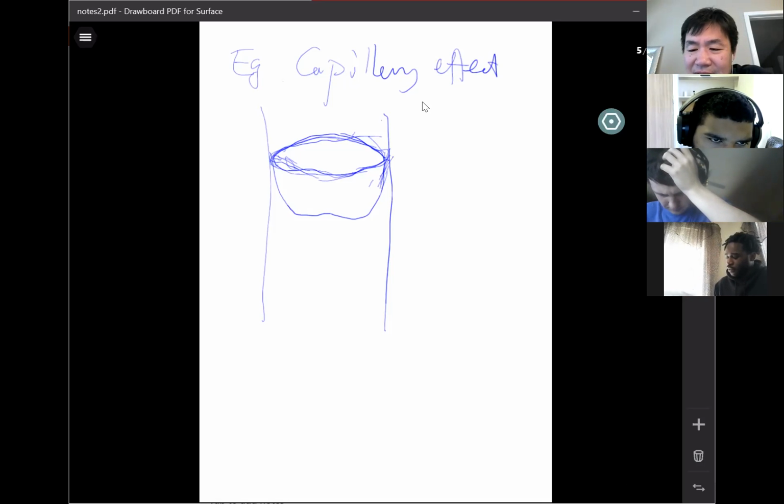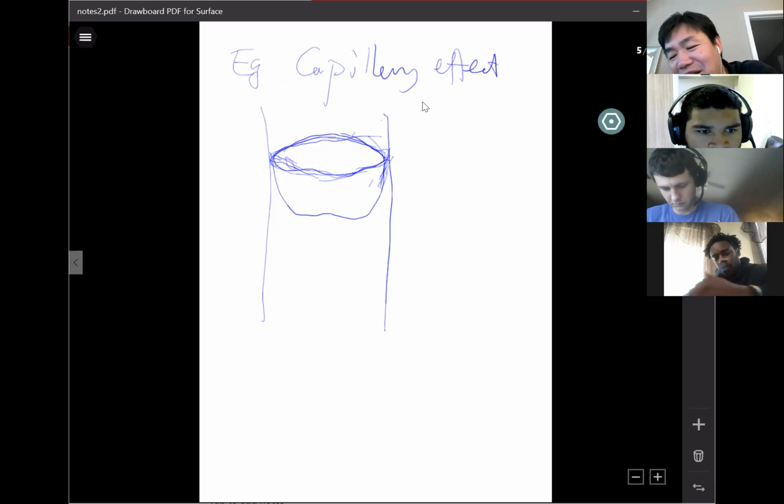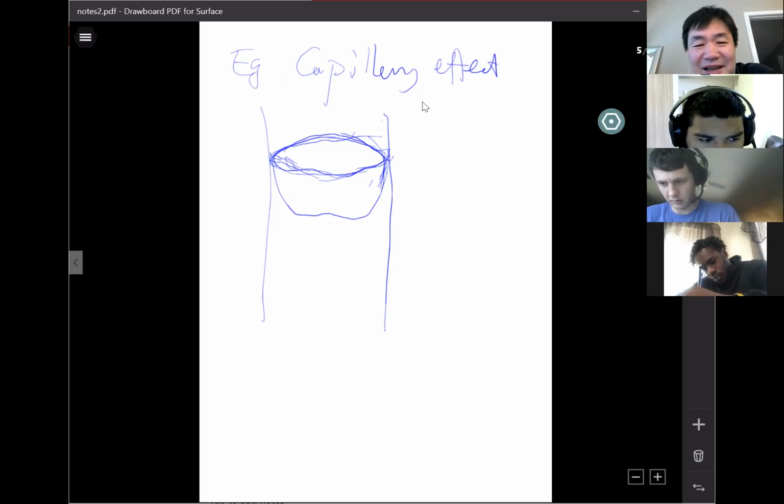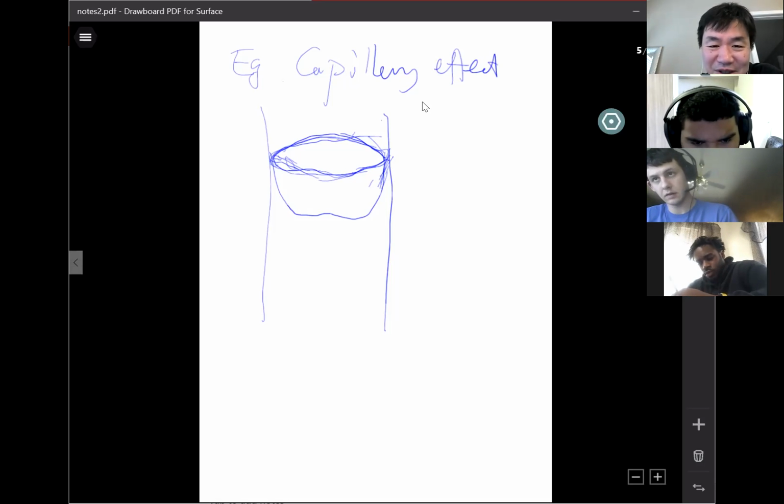Surface tension is perpendicular to the tear line. That's right, perpendicular to the tear line, which is the interface. In this problem, you're not tearing or breaking a dropping particle, so I use the word interface. Perpendicular to the interface, okay? So this is the circumference. Your arrow is going to be perpendicular to it. It can be any direction perpendicular to it, right? You see? Then it's tangential to the surface down here. So that's your direction of the force.